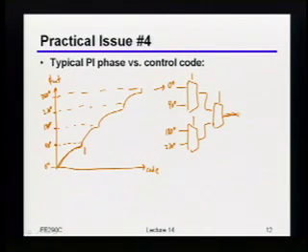I think, Igor, you had your hand up. I mean, the mux structures are not very symmetric, right? Well, what do you mean by that? So you're right, but what do you mean? Well, there's transistor stacking, stuff like that. Okay, but again, let's assume I do a good job, and I make it so that this path, at least nominally, from the standpoint of the bare transistors by themselves, is similar to this path over here. Does that do the mismatch between PMOS and NMOS? That could be there, although that's not quite it.